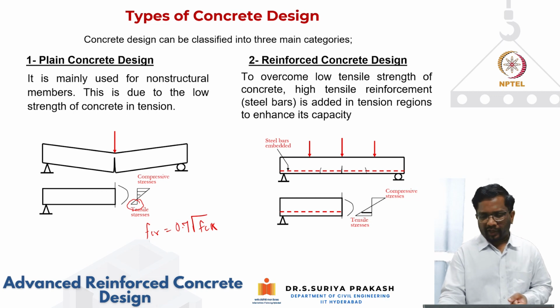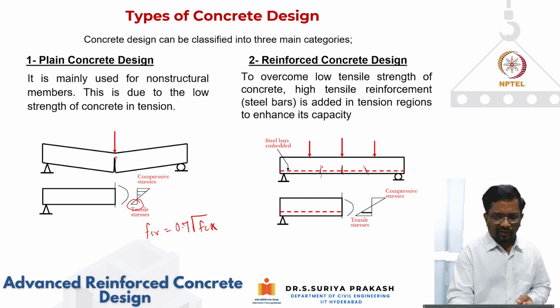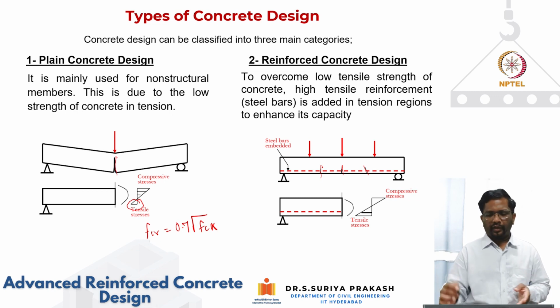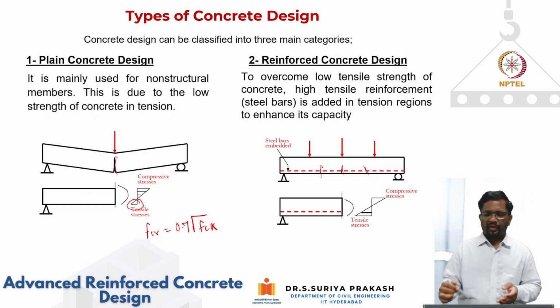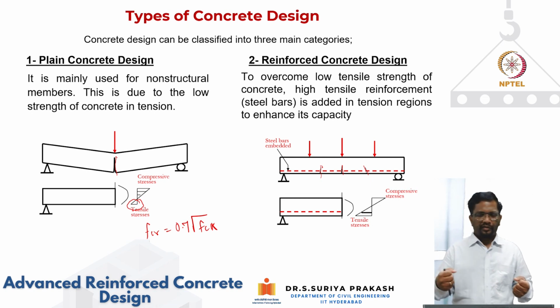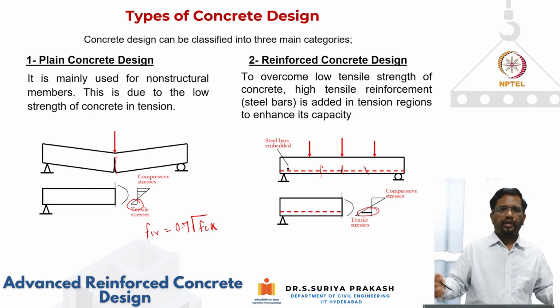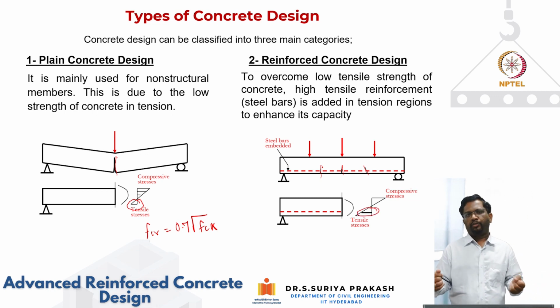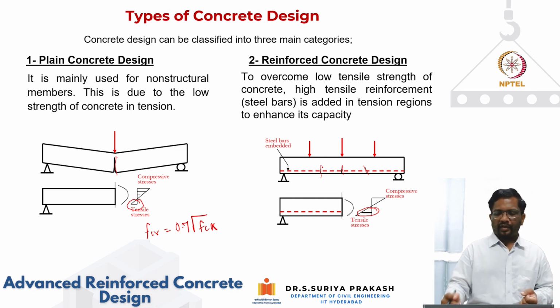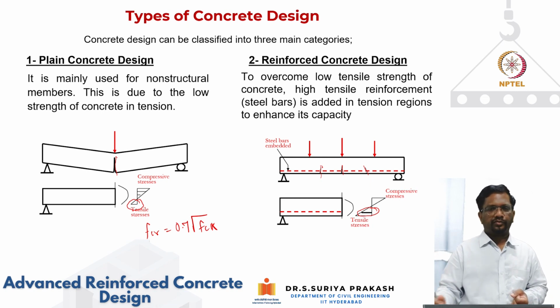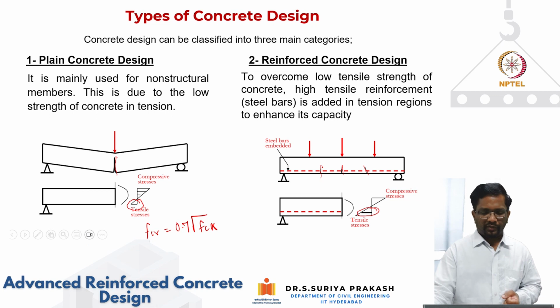Now, though there is a crack like this, the system will not fail. Here, the moment this crack fails, that's it, the failure, right? However, the moment you put reinforcement, the reinforcement will be able to take the tension. And we know that concrete is strong in compression. So now the system can take a large amount of tensile stresses, and then you can increase the capacity. So this is what the objective of this course is going to be.